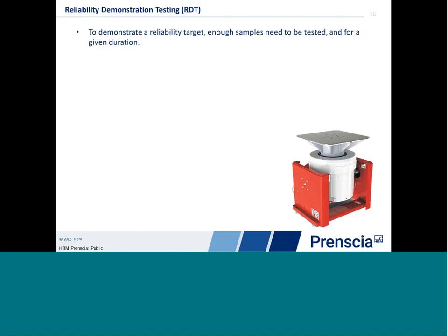One thing we could do is test a lot of samples. We know what the cyclic loading should be on our loader arm when we put it on some kind of test apparatus. We looked at 50,000 cycles at plus or minus 850 pounds to be the equivalent of some customer usage scenario.